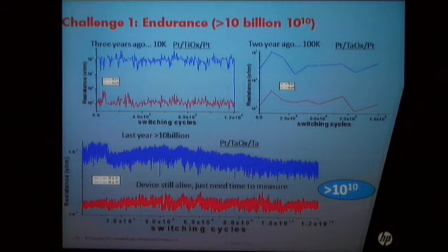So the answer is that we actually undersample the switching here, meaning we measure probably after every 0.5 million cycles because we cannot measure every data point after switching, and it's just too big. Even this has 20,000 data points here. It makes the PowerPoint very big. But anyway, we didn't measure every one, but from all the ones we measured, we do not find any error or unswitching event.